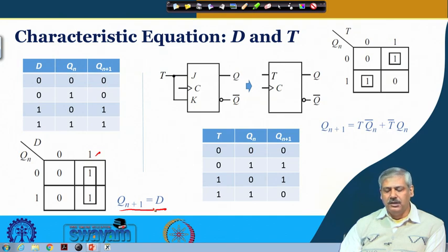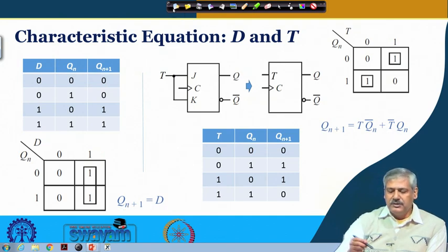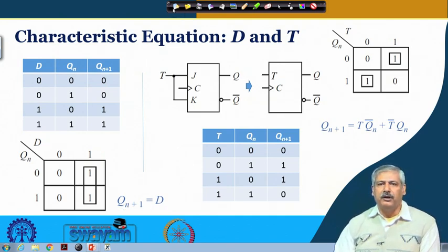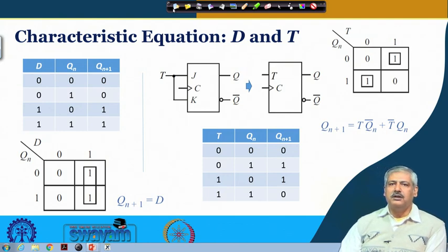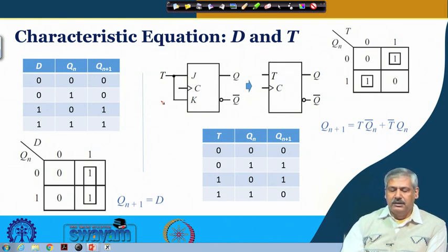Clear? So, here we introduce another flip-flop, which we call T flip-flop or toggle flip-flop. If we try to visualize what would be the internal logic circuit of T flip-flop, we refer to how JK flip-flop is made, and then connect both the inputs J and K tied together.